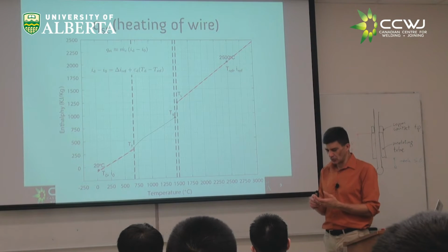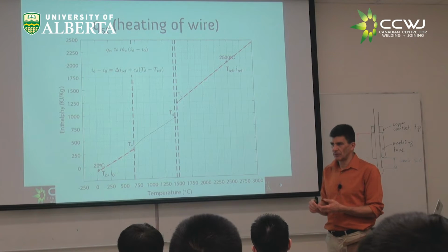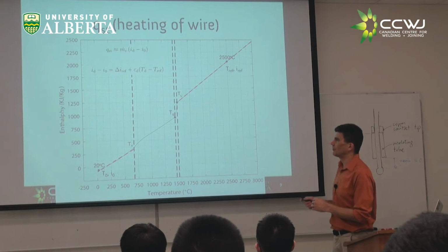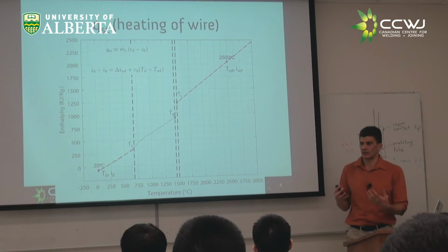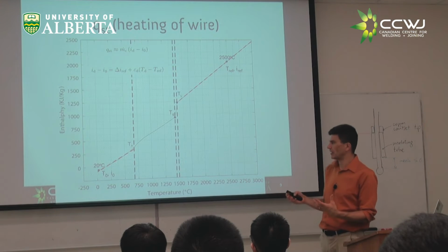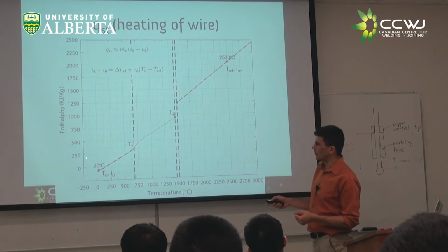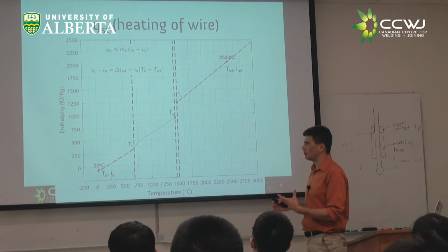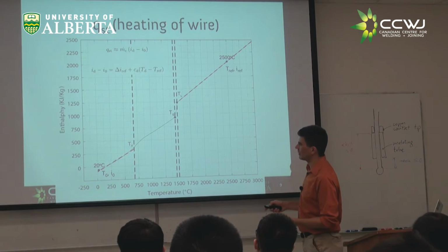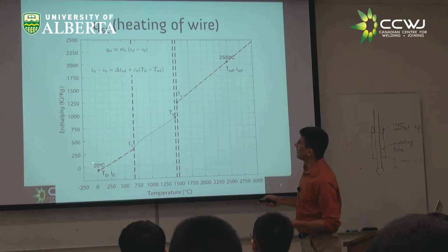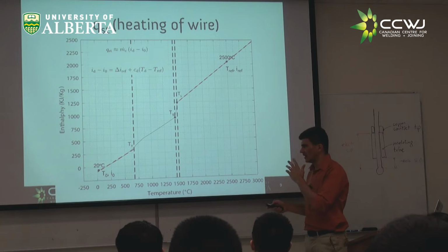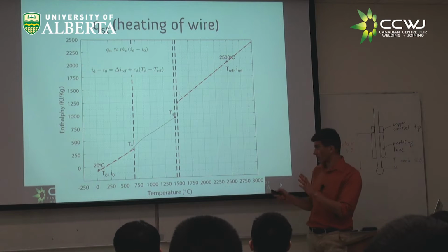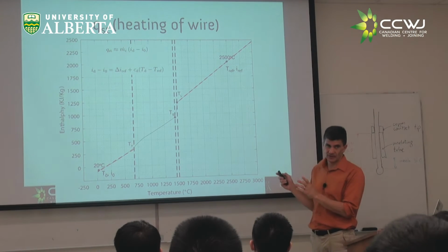So we have two things coming in, one thing being generated, and the heat is being stored in the form of enthalpy. If you use Thermo-Calc or those computational thermodynamics packages, you can graph the enthalpy, that is the amount of heat the wire material takes as a function of temperature. Let's say we start at 20 degrees, and we end up at 2500 degrees. At 20 degrees, what's the state? Solid, right? At 2500 degrees, liquid.